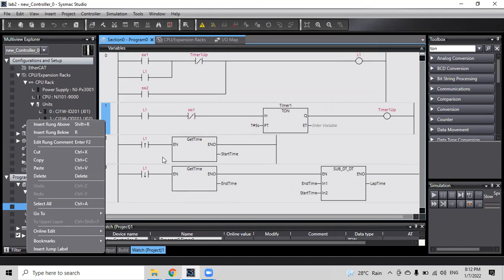First of all, type C, you need input L1. Then after the L1, you press the I key on the keyboard, then you can have a block like this.